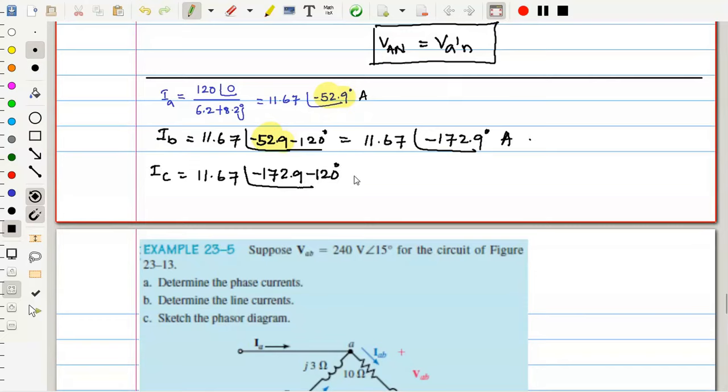You can take either of the things, so you should understand clearly. What is this angle? This angle is the B phase corresponding angle. From B, C should lag by 120 degrees. If I consider A, from A it should lag by minus 240 or plus 120. Are you getting? If you have doubt in that way, I can make the expression in this way.